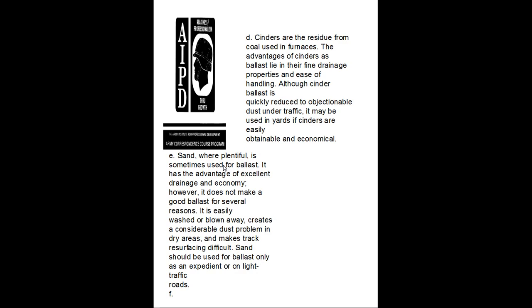Cinder ballast has fine drainage properties and is easier to handle, although it is quickly reduced to dust under traffic. It may be used in yards, and cinders are easily obtainable and economical.